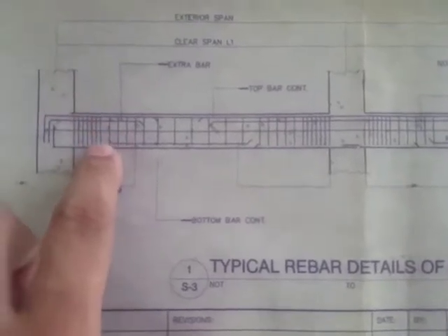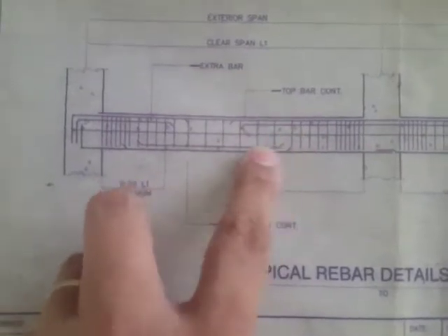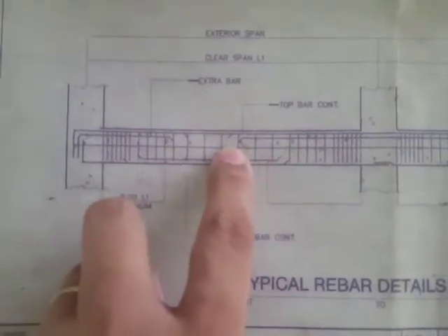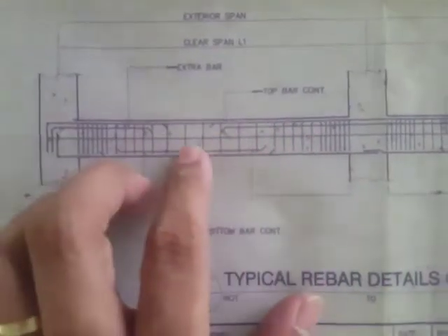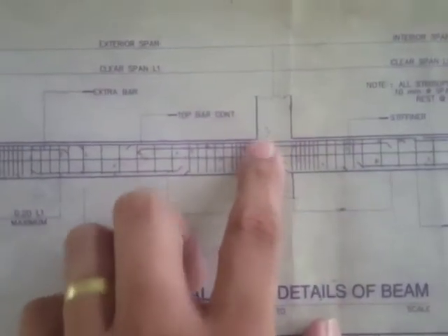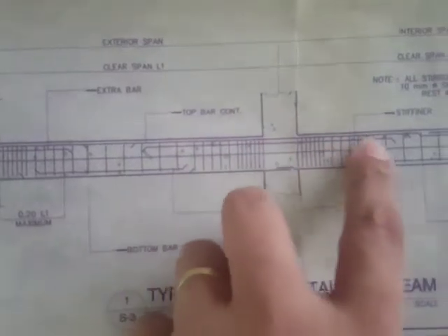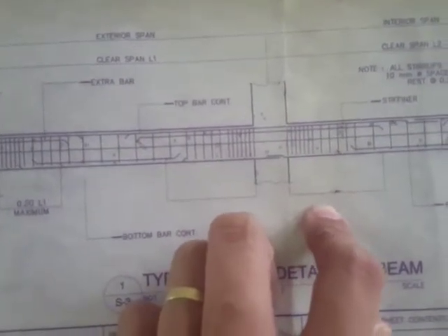And then there is also another cut bars here at the bottom. Okay, cut bars that's along the mid span, and then at this support side again, you will have a top bar, cut bars or extra bars on top. But if it's an interior column, then it is continuous until the point 2 L2.